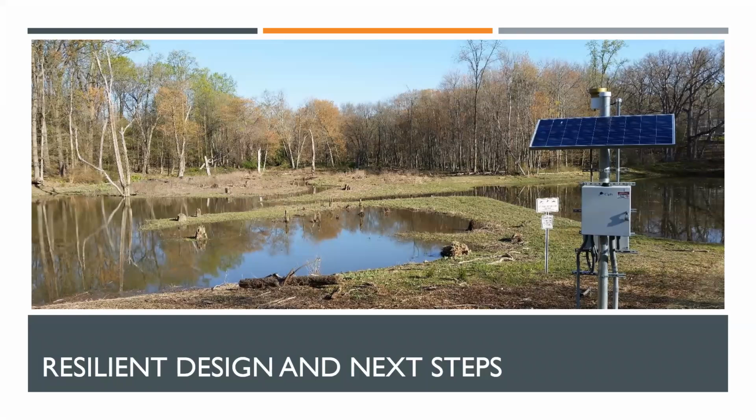So there are methods, and they recommend some for filling out the lower range of your IDF curves down to the 10, 15 minute duration events and things like that for those really short bursts of intense rainfall. They feel pretty confident in the methods that they have. So they'll have documentation on that within their tool to help address some of those questions.